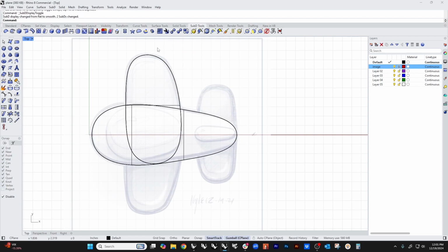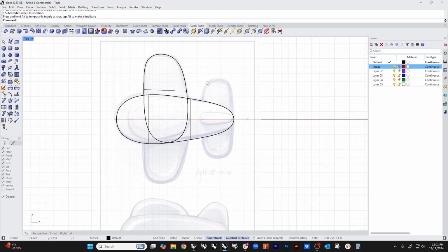Tab. And you can do edits in smooth mode, but I always caution that, because you want to make sure that you are getting your detail right in box mode before you start messing around with smooth mode, because you can really make a mess out of your box mode if you want to.